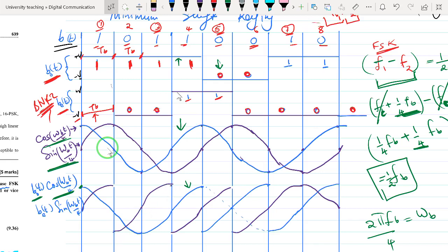And then there's another phase shift. So it will change phase again by 180 degrees. Instead of going down, they start going up. So this is the one that is represented by black. Similarly, at this point, there is a change in phase from +1, or from positive voltage to negative voltage. Again, the black one changes sign. Instead of going down, it has a 180 degrees phase shift. Then for the remaining duration, there is no phase shift. It remains continuous until the very end.